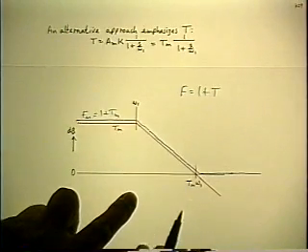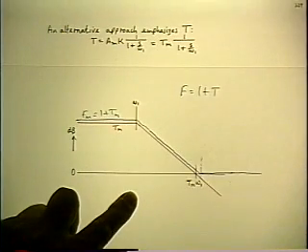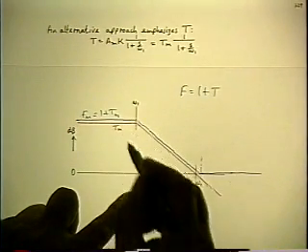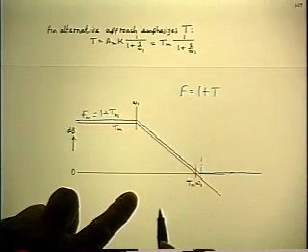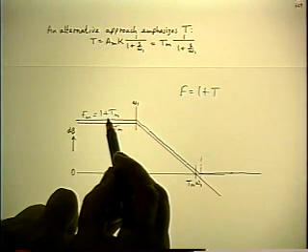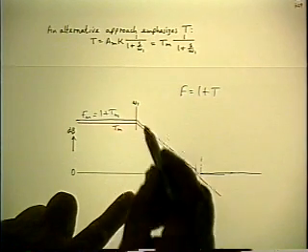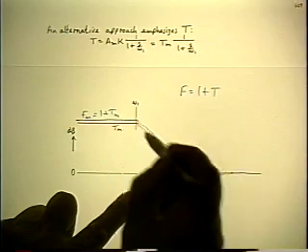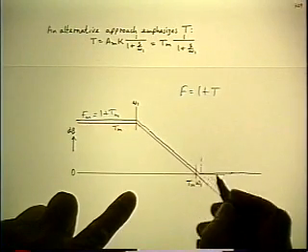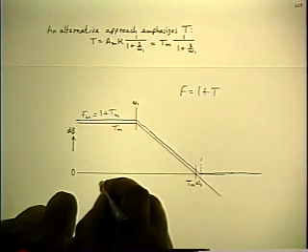If it's right, what is the value of this frequency? Well, gain bandwidth trade-off gives it to you right away. Because down here the magnitude is Fm. Down here the magnitude is 1. Here the corner frequency is omega 1. Therefore this corner frequency has the same ratio to omega 1 as this magnitude to 1.